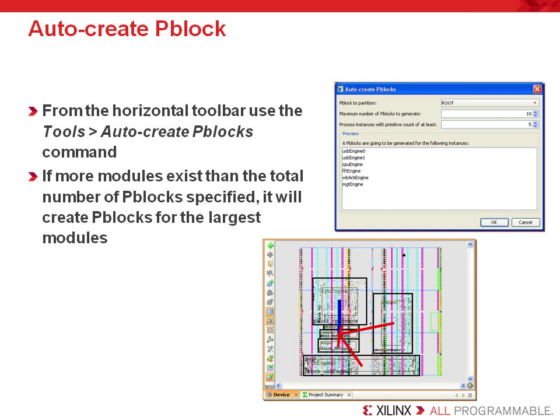PlanAhead enables automatic Pblock placement using the AutoCreate Pblocks command. This method is used primarily to create top-level Pblocks to view the data flow of the design and to understand the relative size and relationship between the various logic modules in the design. Normally, the designer has some concept of the critical modules and circuitry in the design and begins floor planning with those modules.